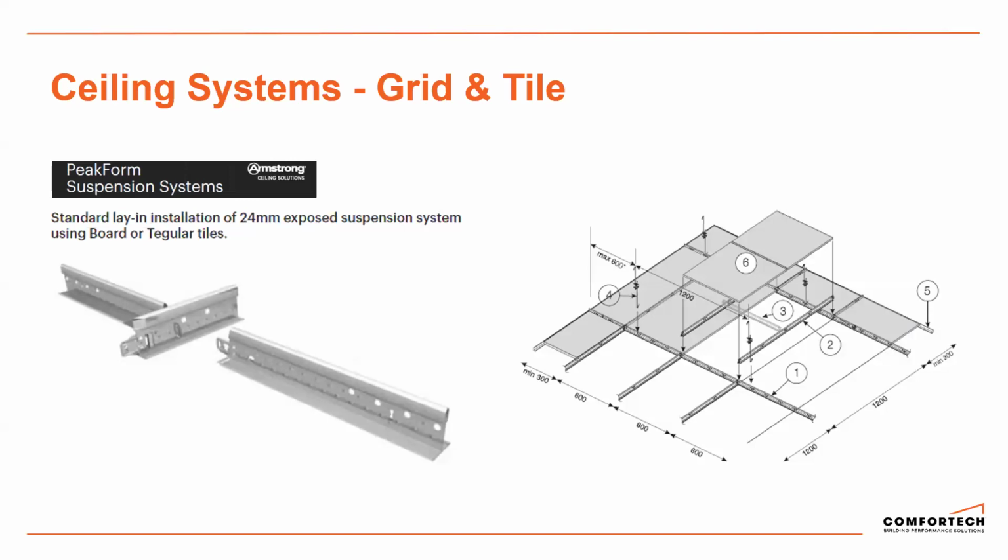In seismic calculations, the cross tee run, the length of our cross tee run, is normally double the maximum main tee. To give you an example, if our main tees can run 10 meters before we need a seismic gap, we can normally get 20 meters out of our cross tees. So ideally, you want your cross tees running the length of the building, which is generally longer.